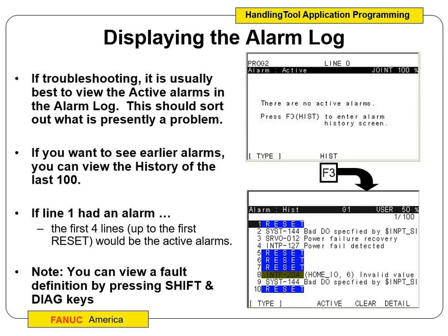Okay, we can also always check the alarm log. Alright, so we can hit menu, go down to alarms, and we can take a look at the alarm log and see what's happened. It'll tell us, looking at the screen here, we can see if it's a servo 12. We had a servo 62 error not too long ago, so the batteries all died, so none of the axis, none of the servos would work. So we had to put new batteries in the FANUC and then remaster it.